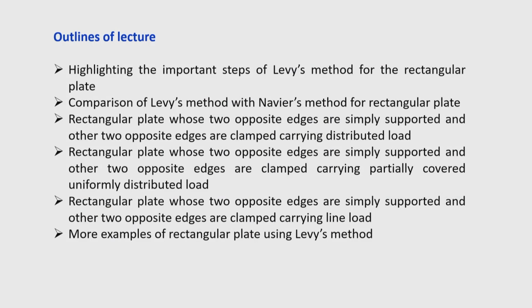Okay. So, today's lecture outline will highlight the important steps of Levy's method for rectangular plate, and a comparison of Levy's method with Navier's method. Then we will illustrate a problem of a rectangular plate whose two opposite edges are simply supported and the other two opposite edges are clamped, and the plate carries a uniformly distributed load.